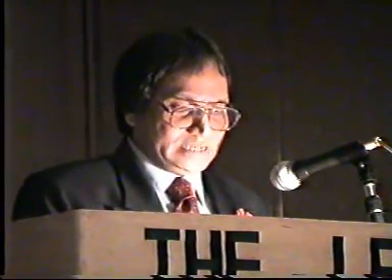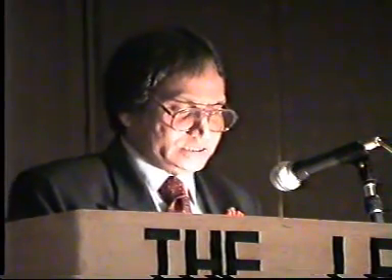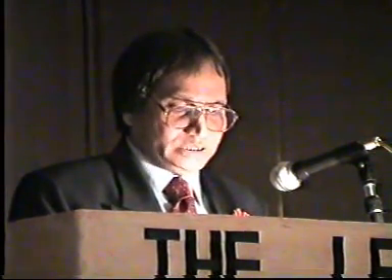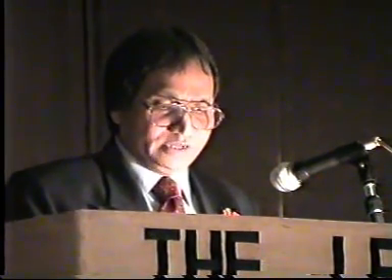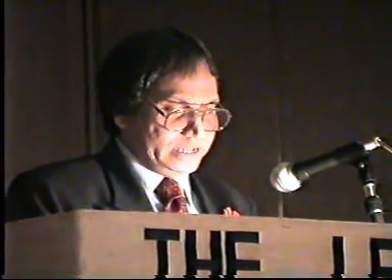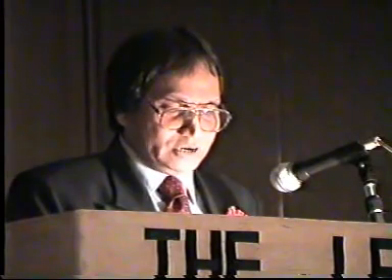The glass assemblies have to be very carefully arranged and well clamped before any work is started. They cannot hold pressure. It is also impossible to distill anything under high vacuum, say 0.5 torr, under stirred condition in a small glass assembly. Except for providing visual aid, the glass assembly does not provide any special advantage unless, of course, a corrosive reagent, which cannot be handled in a stainless steel reactor, is used for reaction.